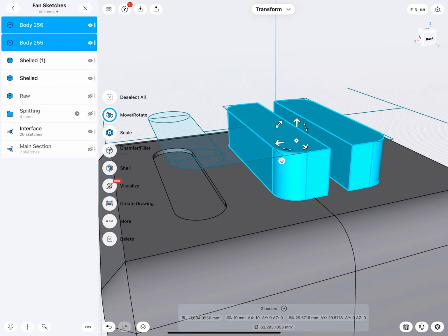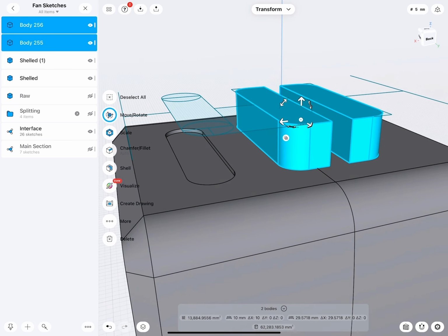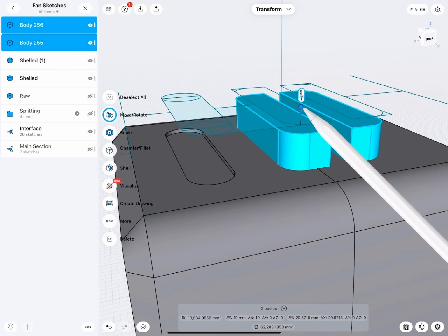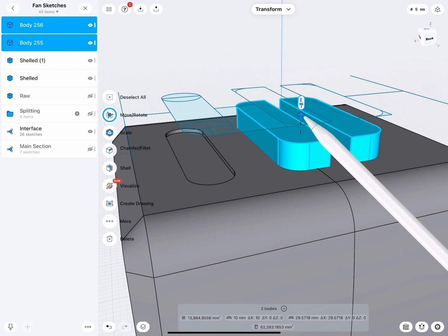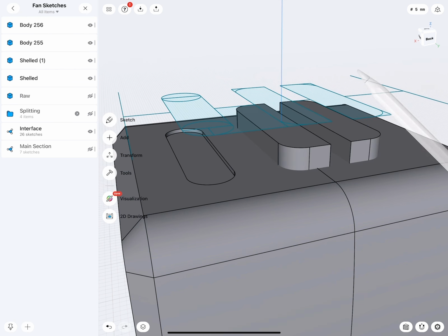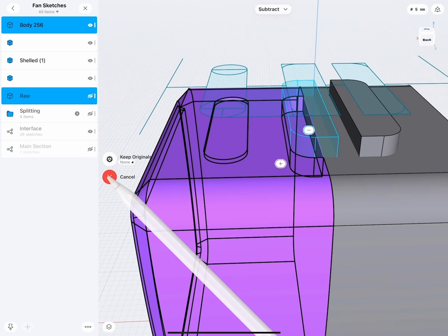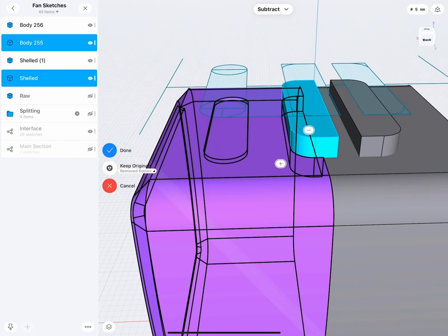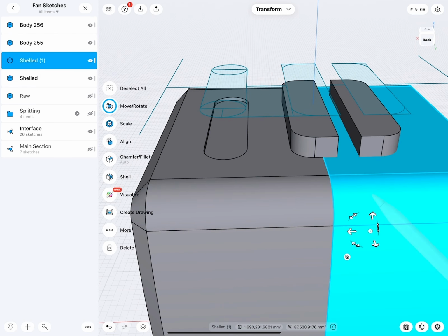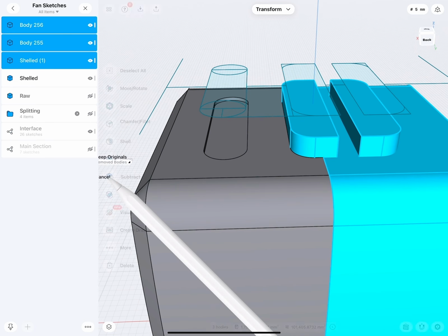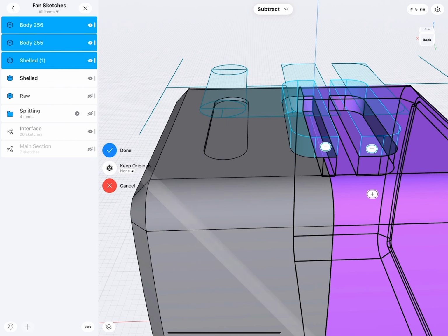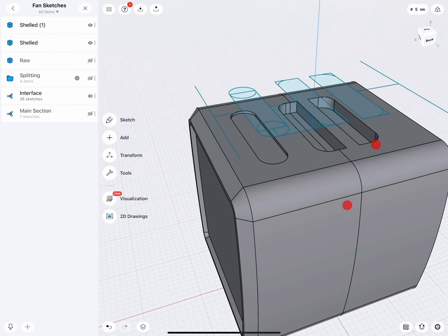Now these two extrusions sit right on top, and then I can move those down, let's say 10 millimeters. Very good. From this, I can remove this, but keep the body this time. And then from this half, these two I remove, but do not keep the body.